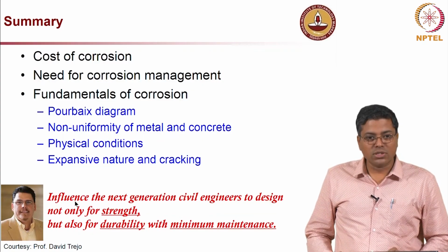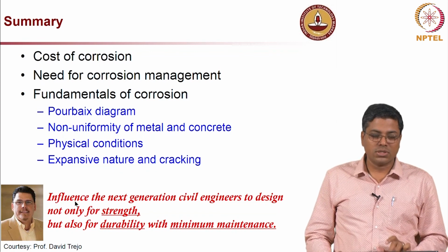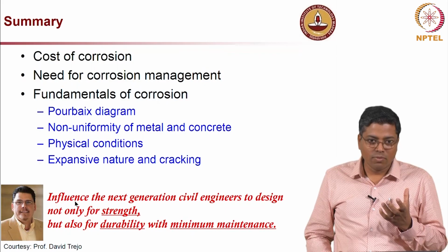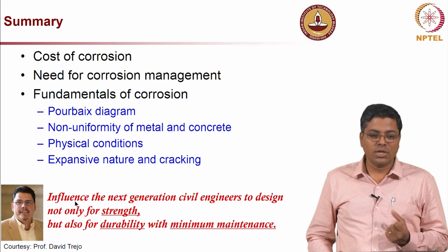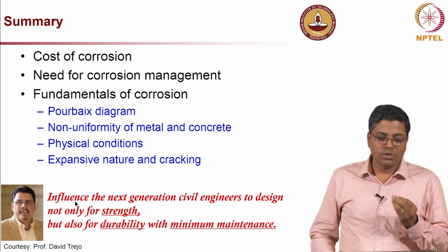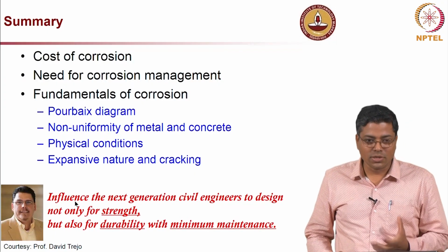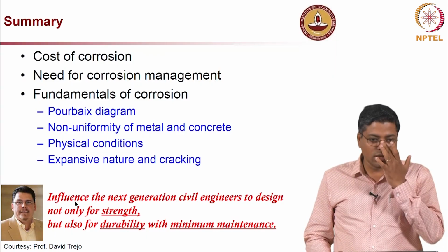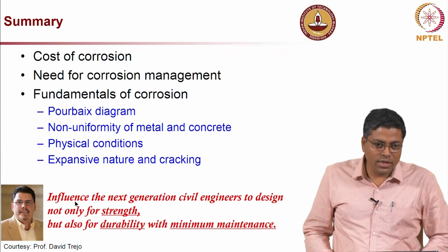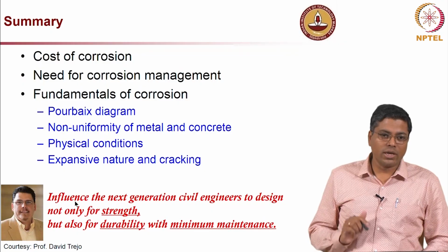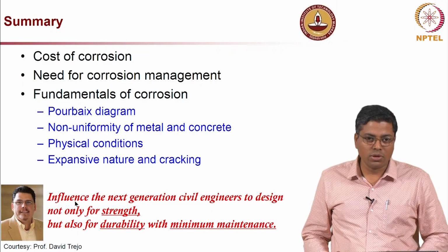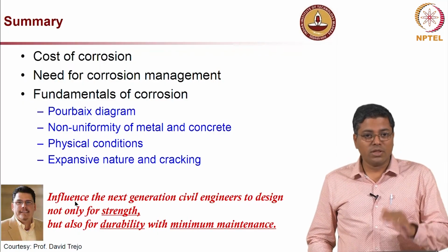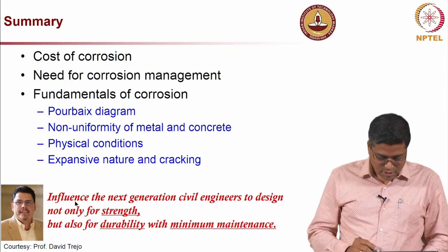It is very important for us to consider this today, because for most civil engineers, when we talk about concrete, one of the important parameters that comes to their mind is strength, or to be precise, 28-day compressive strength. That is not going to give you durability for the structure. So, you have to really think about how we can ensure durability, not by spending a lot of money later on, but with minimal maintenance. Thank you.